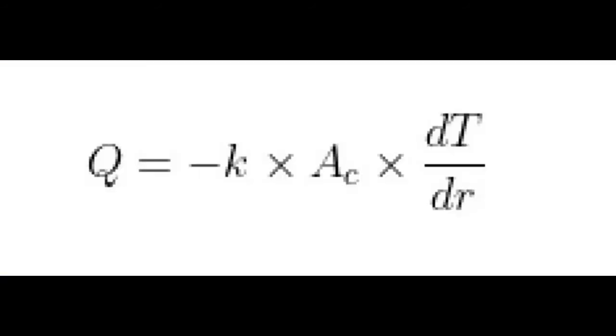Next we will model the eggshell as a sphere. The spherical shape approximates the eggshell geometry much better than the long cylinder or plane wall. The rate of heat transfer will be calculated using that derived for a sphere. The Fourier law of conduction for the heat transfer system is shown in the clip, and its general form is exactly similar to that of the long cylinder.